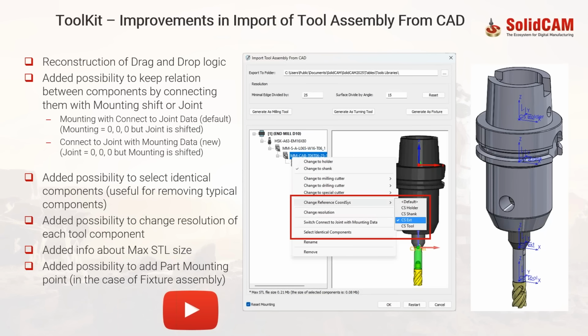That's extremely important if you want to work with the optimization of your 3D models. It is just not enough to take the general resolution settings, because for some holders and cutters that would not be enough.